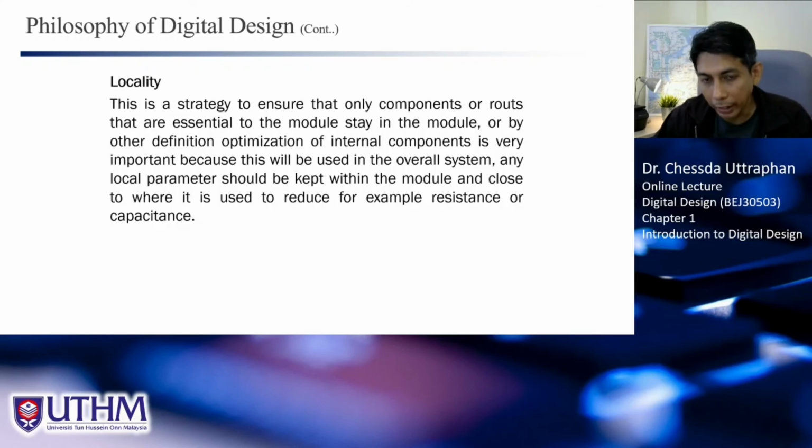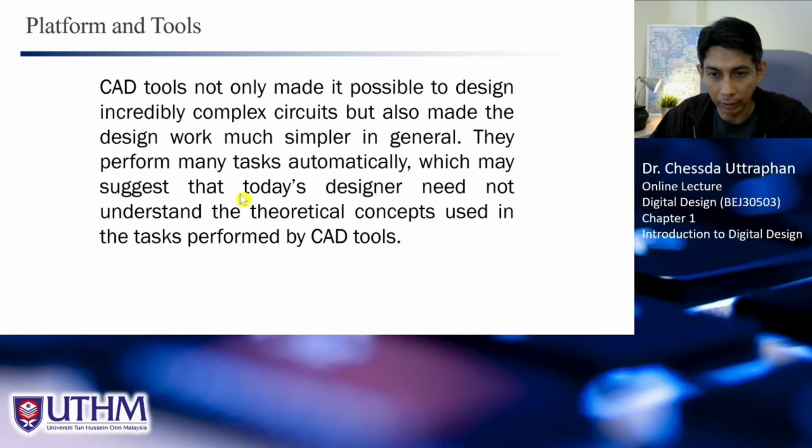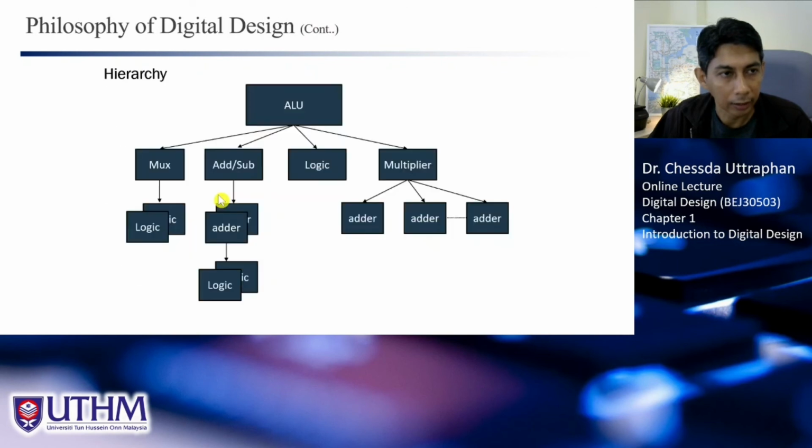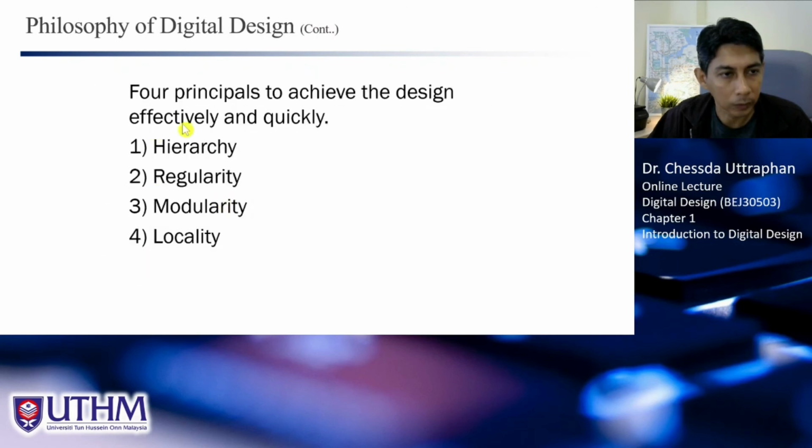So we need to make sure that when we reduce the power consumption of this module, we will not affect the power consumption of other modules. So that is locality. It means that everything that we do in our module does not affect the neighboring module. All right. So again, go back to this. We have 4 principles, but we will focus on hierarchy and regularity in our course. The others will be in the VLSI course.